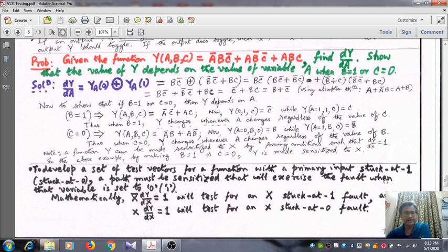when a transistor, say NMOS transistor, is stuck at 0. Stuck at 0 means what? Even though you set the voltage to high, a channel cannot exist because somehow the outermost metal conductor is disconnected from the polysilicon gate. So even though you are making the gate voltage high, the transistor always remains cut off.